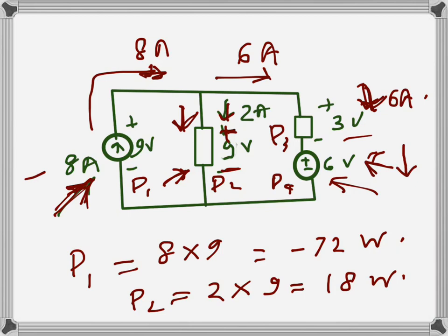in this direction, so the voltage source is supposed to transfer current, it supplies current from the positive terminal and the current enters through the negative terminal. That's what happens. But in this particular circuit, the voltage source is actually absorbing power because current is entering through the positive terminal and leaving through the negative terminal. We can see current is going downwards, so entering through the positive terminal and leaving through the negative terminal. So for this particular circuit, the voltage source is also acting as a passive element. It is absorbing power, not supplying power.